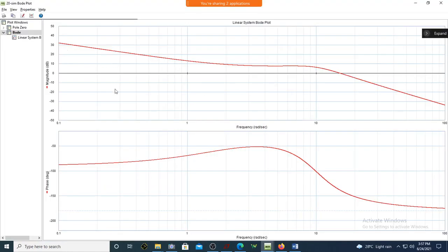See here, this is a plot. Can you see this is going positive? Not positive, it is actually going from minus 90 degrees slightly more positive towards minus 80, minus 50, and then again it comes down. Why is it slightly becoming positive, from minus 90 up to minus 50? Because of a zero. A zero will contribute and has to move this angle in the positive direction, because a zero will actually give positive phase.